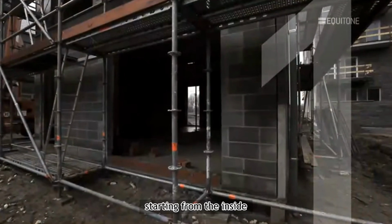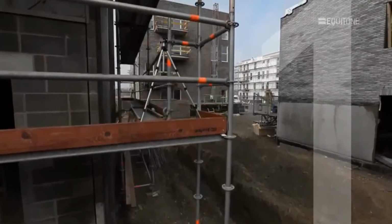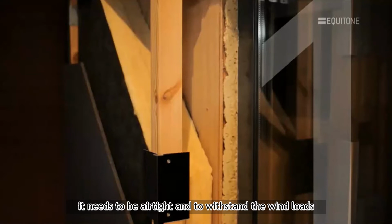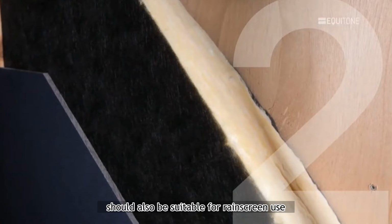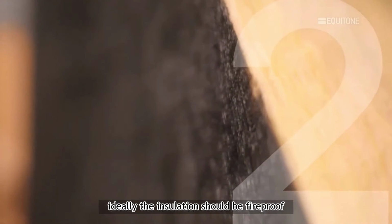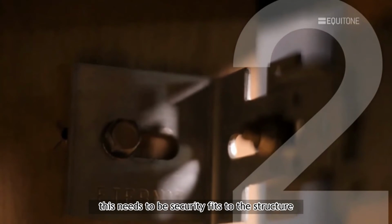In addition to the outer skin, a number of other elements need to come together. Starting from the inside, the internal structural wall can be of masonry or lightweight construction. It needs to be airtight and to withstand the wind loads that will be placed on the building. The insulation, thick enough to suit the building's function, should also be suitable for rain screen use. Ideally, the insulation should be fireproof and permeable to allow any water vapour to pass from inside the building into the cavity. This needs to be securely fixed to the structure and fit tightly around the supporting frame.